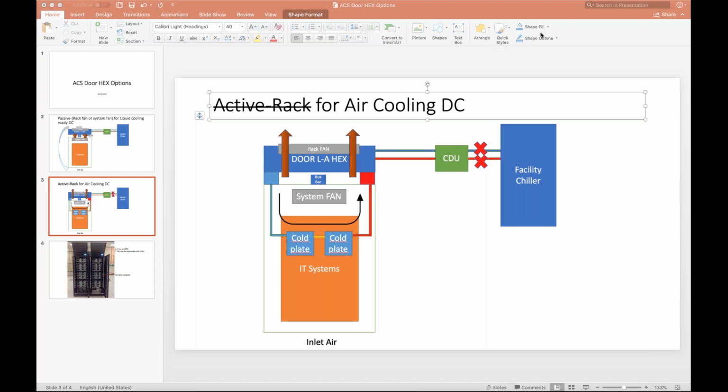Okay, so I think also, just to comment on the dew point, 57 or 58 Fahrenheit is kind of an average dew point for most data centers that are properly sealed. So if you're using, let's say, 65 degree or 74 degree water from your cooling tower, it's quite achievable without much risk of condensation.